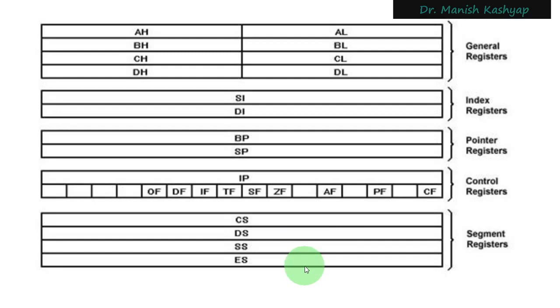In 8086 microprocessor, the externally interfaced memory is of 1 megabyte, and we said that inside that 1 megabyte memory, you are free to create your code segment, your data segment, your stack segment, and your extra segment. Since the memory is of 1 megabyte, we have got 20 bits of address for every location, or in hexadecimal we can say that 5 hexadecimal digits address will be there for every external memory